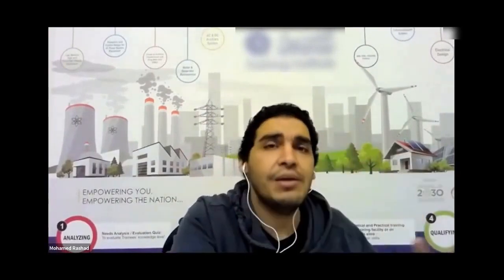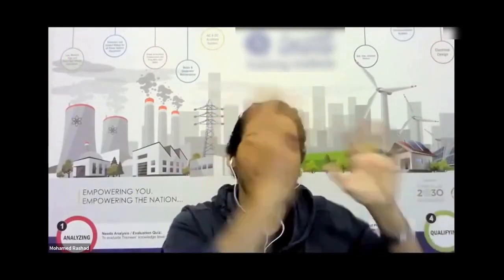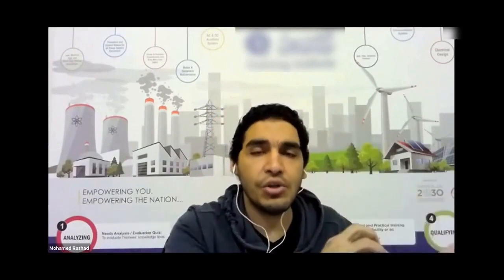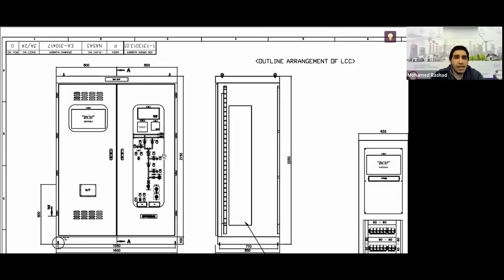And the other part is the JS, which contains the mechanism of the breaker, including the motors of the breaker, the spring of the breaker, the motor of the disconnector, and the air switch, the current and voltage transformer. It contains the primary components themselves that open and close, and their control circuits are located in the LCC panel, which is the local control cabinet that I am now explaining. I'm explaining our schematic diagram.